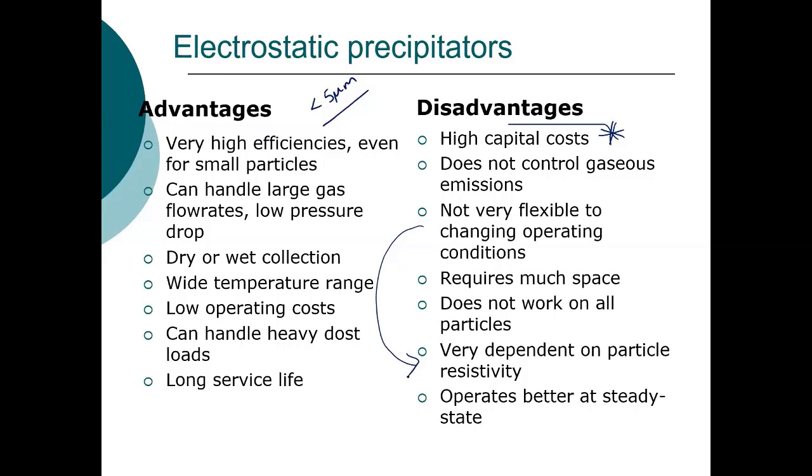They also require a lot of space. They don't work on all particles. They don't work on particles with very low or very high electric resistivity. They also operate better at steady state. So changing operating conditions can have a detrimental impact.